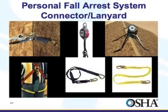Lanyards should have a minimum breaking strength of 5,000 pounds. Self-retracting lifelines and lanyards, which automatically limit free fall distance to 2 feet or less, shall be capable of sustaining a minimum load of 3,000 pounds in the fully extended position. Self-retracting lifelines and lanyards, which do not limit free fall distance to 2 feet or less, rip-stitch lanyards, and tearing and deforming lanyards shall be capable of sustaining a minimum load of 5,000 pounds in the fully extended positions.